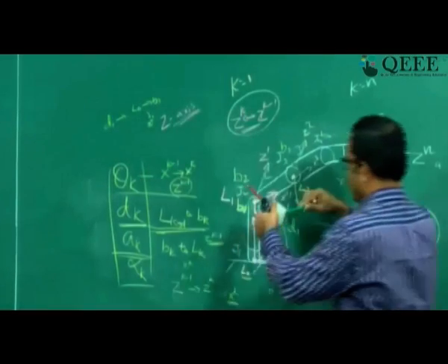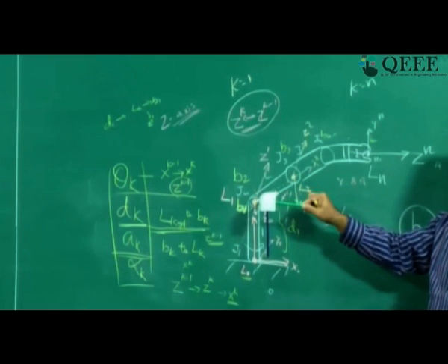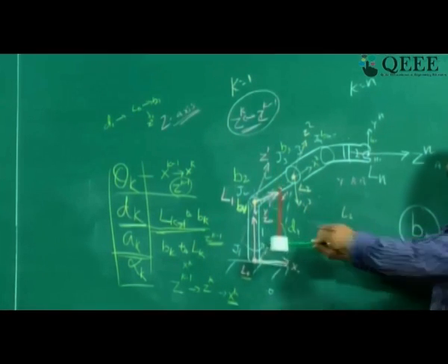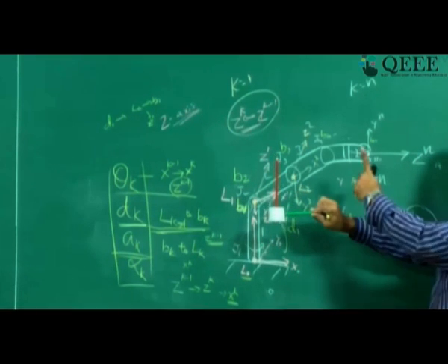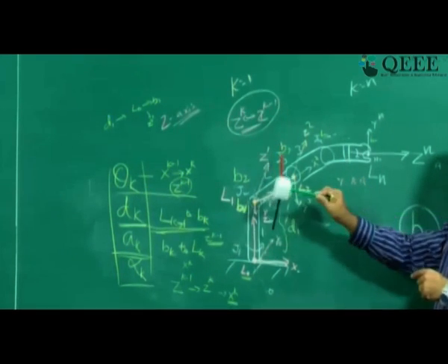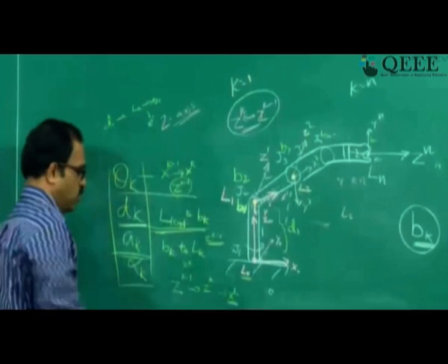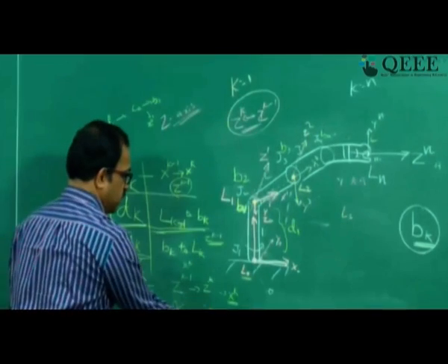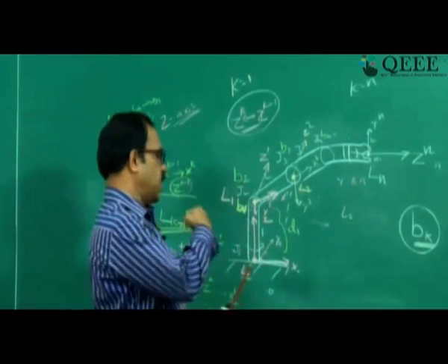So this is the x-axis here, the x-axis for this joint. How much has it rotated to become this position? It was initially like this, and now it has rotated by 90 degrees clockwise. So this clockwise rotation of 90 degrees is the alpha k here. Like this we need to look at each joint and identify the alpha for each one. So alpha 1 will be 90 degrees counterclockwise. Clockwise is always taken as minus 90, counterclockwise is taken as positive. So clockwise is minus, counterclockwise is plus.